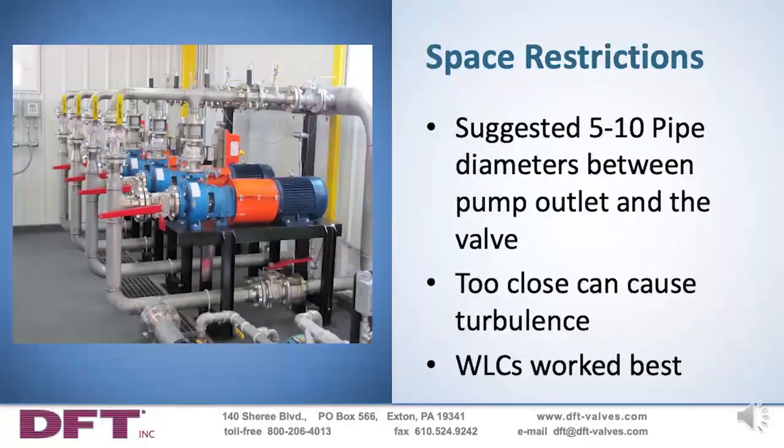One of the most common problems with pumps is their demanding spatial requirements. Because pumps tend to generate a fair amount of noise during their operation, they're usually put in special pump rooms. However, these rooms are not often sized with all the space requirements in mind that are needed for the valves, the fittings, and all the piping, so you wind up with a very tight fit and limited space for everything.